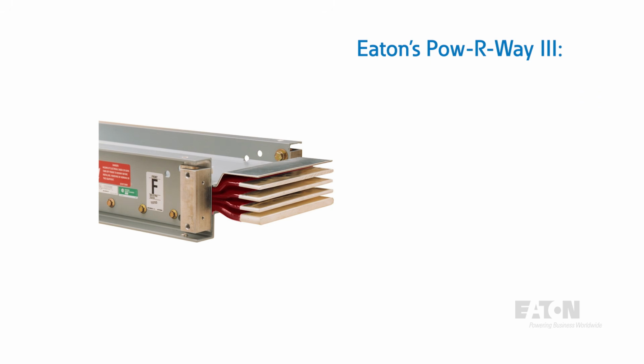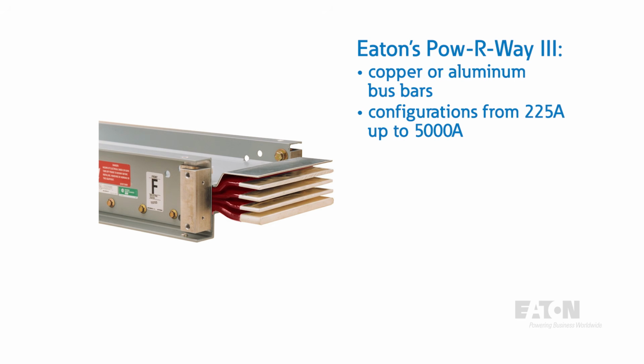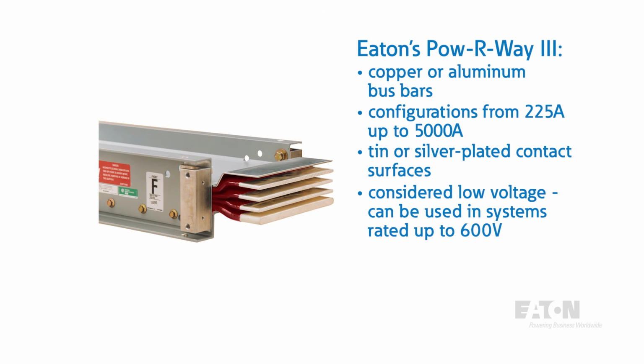piece of busway. Eaton's PowerWay 3 sandwich-style busway is available in either copper or aluminum bus bars with configurations from 225 amps up to 5,000, and either option will have tin or silver-plated contact surfaces depending on specification. PowerWay 3 is considered low voltage and can be applied to any system rated up to 600 volts.